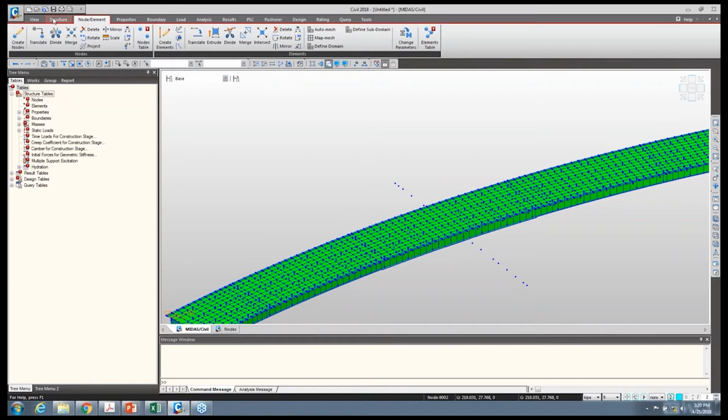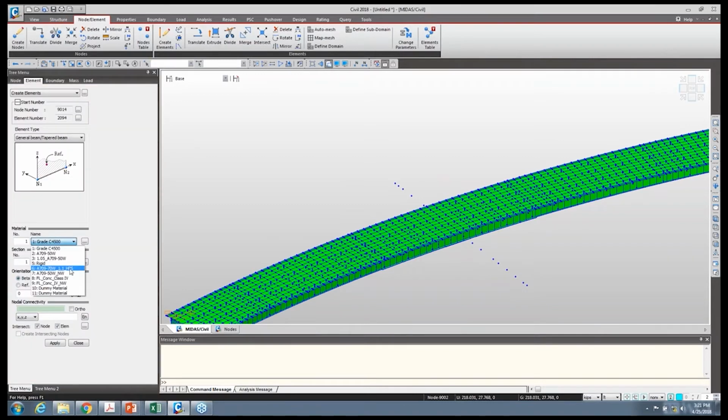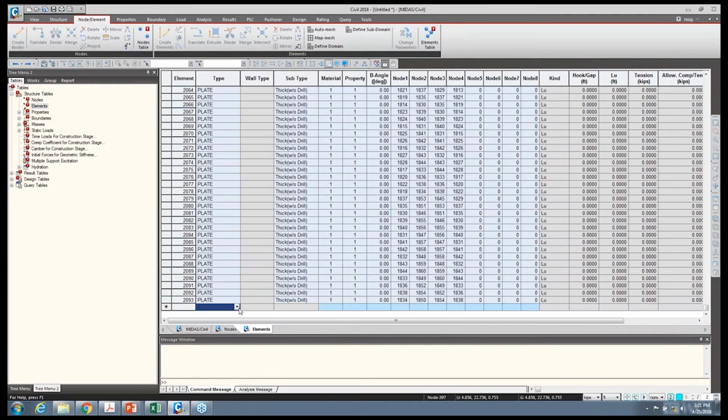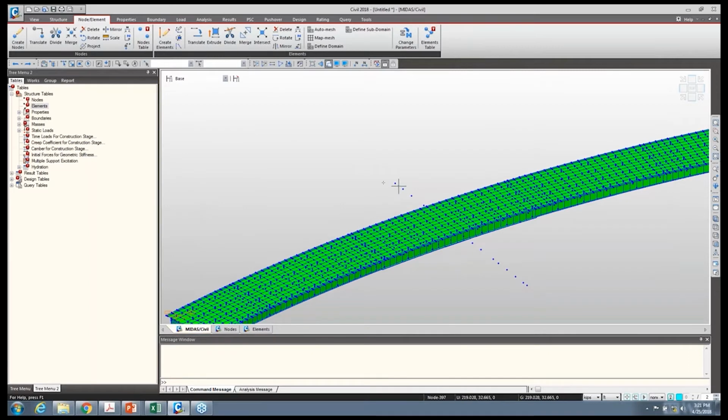You could also do the same thing using the table, similar to the elements or the nodes previously shown. And we can go ahead and select a beam member and fill out all of our properties. In order to make things just a little more simple, what I'm going to recommend is that we once again rely on the shell command. So I've already predetermined, using the same designation for those same members, a group of text strings to do the shell command. And I'm going to use the element insert. And so as you see here now, I have all of my straddle pier ready to go.